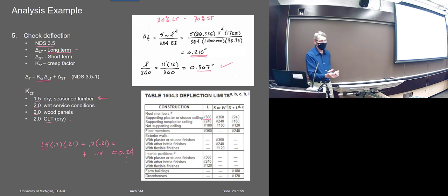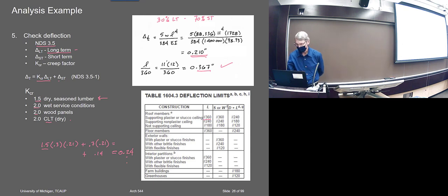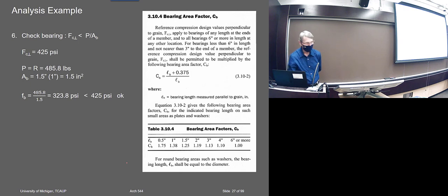Most of the deflection limits are based on bounce, right? So creep wouldn't even apply to this. Creep would be something that matters if it deflected so much that it caused damage to the ceiling or something under it, or was sagging so much that it somehow was a problem. Not the bounciness of it, which is normally what those deflection limits are about.